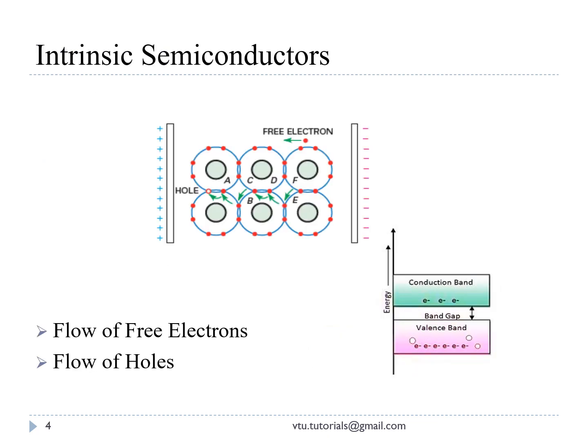A semiconductor in its pure form is called an intrinsic semiconductor, and this is the band diagram for an intrinsic semiconductor. Here we see that the valence band is completely full and the conduction band has a few free electrons. At absolute zero temperature, the conduction band will be empty and the valence band completely filled, and it acts as an insulator.